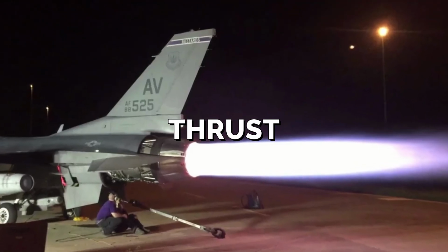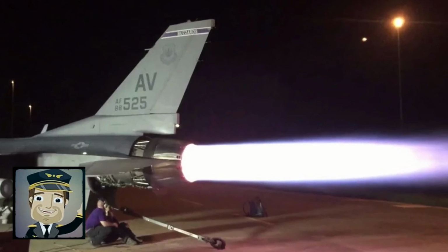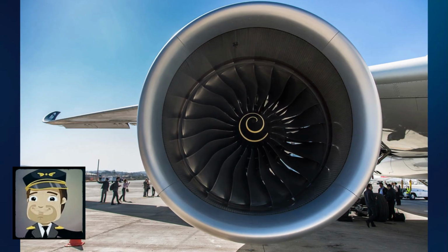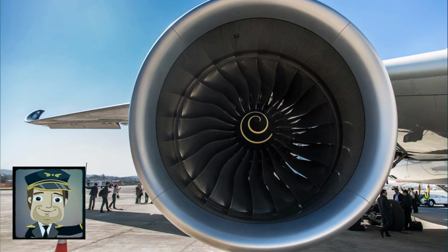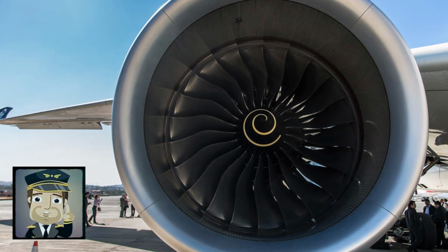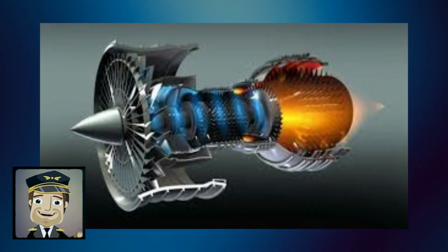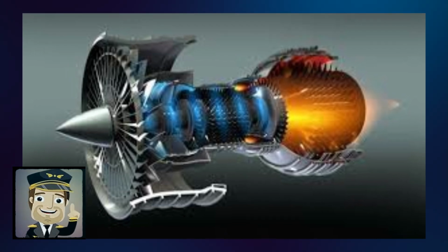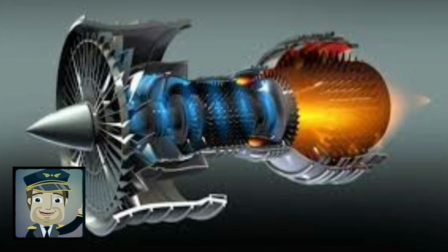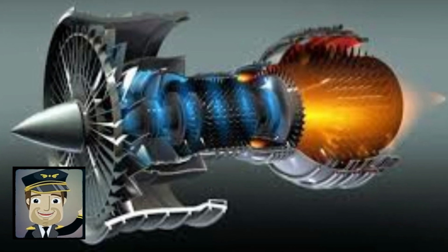While a turbojet engine uses all the engine's output to produce thrust in the form of a hot, high-velocity exhaust gas jet, a turbofan's cool low-velocity bypass air yields between 30% and 70% of the total thrust produced by a turbofan system. The thrust generated by a turbofan depends on the effective exhaust velocity of the total exhaust, as with any jet engine. But because two exhaust jets are present, the thrust equation can be expanded.